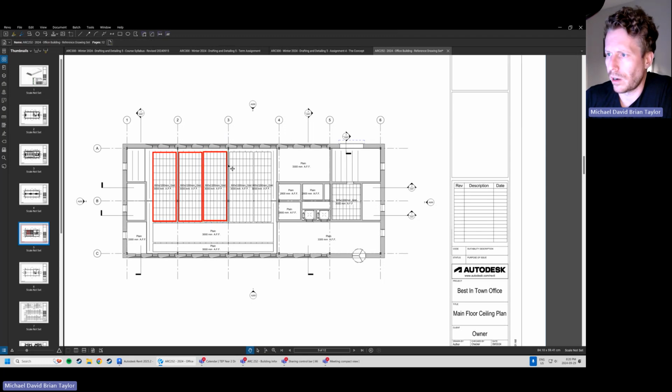And then why don't I use a different color? These are actually what we do for the automatic ceilings. We could make them as a sketch ceiling as well, but why don't I just make this blue here? This is an automatic ceiling because we have what are called the existing walls, right? So we have the existing walls that frame it, and we can use that automatic ceiling tool to get there. You might notice we've also got, let's make a little cloud here, these tags.